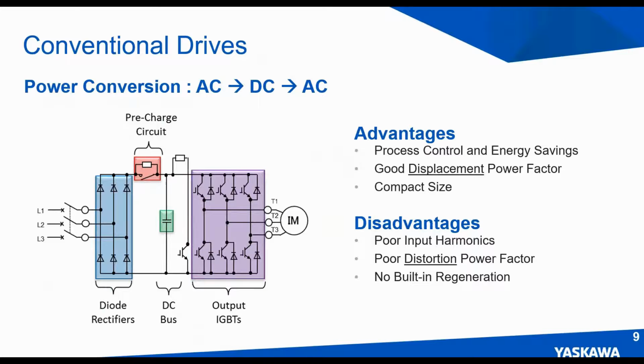Let's look at a regular drive. From their advantages perspective, drives provide motor control, energy savings, and have very good displacement power factor, all in a very compact size. However, their input current can contain high harmonics. This leads to poor distortion power factor and a limited true power factor. When it comes to today's topic, standard drives have no built-in regenerative capabilities.